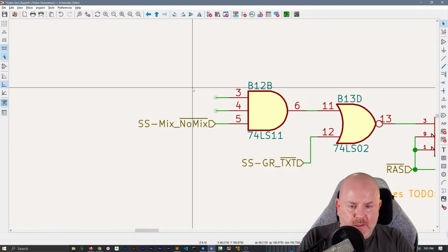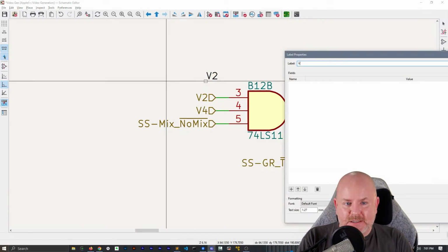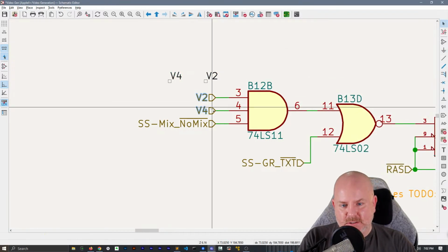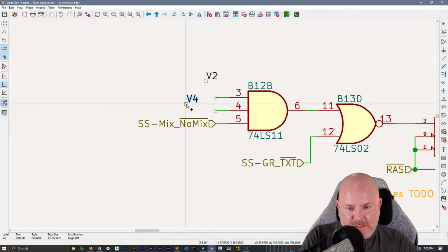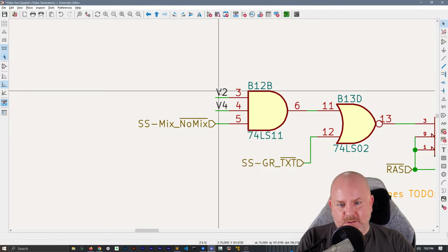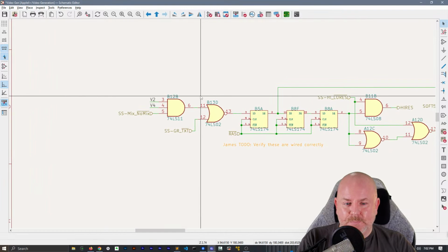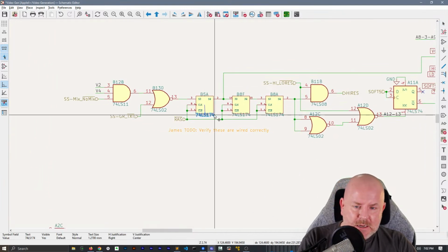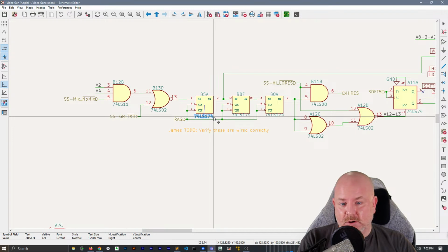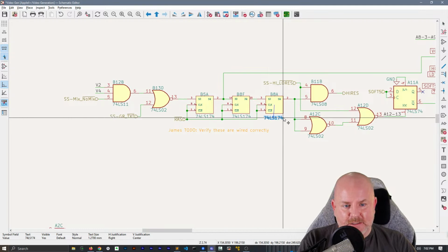There's 80-something chips inside, and the keyboard controller is somewhat custom. It's a masked controller that's actually based on a 6502. And then the ROM chips are custom because they're masked, with the custom code. The RAM chips, I don't think are 7400 series. I don't remember, we'll see it here in a minute. And then the rest of the chips are 7400 series stuff, other than the 555 and the 6502. It's just crazy.